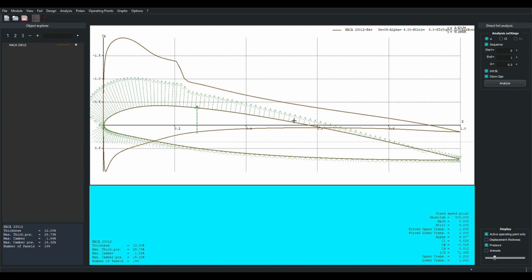And so it's true for air molecules. They're trying to move down the airfoil here. They're moving into a higher pressure region, and they'd prefer not to go, but they got two things pushing them along. Their inertia, we sped them up front here. They have higher velocity, and air molecules have mass, so they have inertia, and then inertia is going to carry them through this, so they're trading off speed for distance as they go through the adverse pressure gradient. They're losing velocity but continuing to move forward, so their inertia is going down, down, down, down, down, and